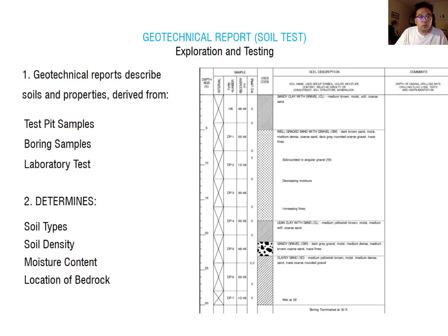So when you see this report, you can find out the depths. You can see the 0 to -30, and you can also find out the soil type, and also the geotech engineer sometimes gives a comment. So you can simply understand what kind of earth composition the soil is for your site. Okay, so you can simply understand the depths and the earth condition from this report.